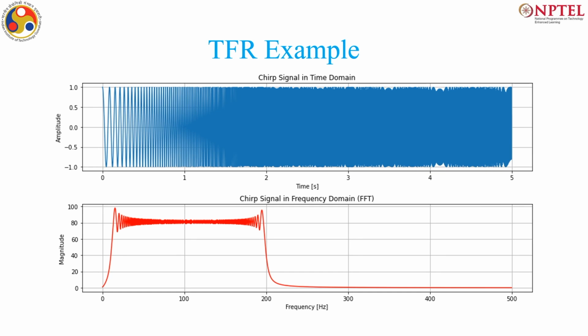So, an example of time frequency representation, one of the best examples, is the chirp signal. Now, where do we hear the word chirp? In the morning we often hear the birds chirping. So, what is so special about a chirp? A chirp is a signal where the frequency slowly increases or decreases with time. In a linear chirp the frequency increases or decreases linearly with time, and this is an example of a linear chirp, and this is the spectra of a chirp.